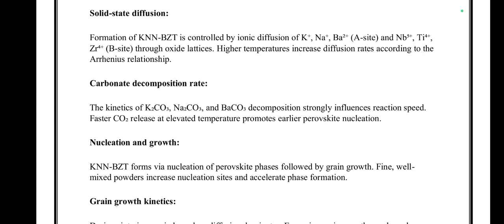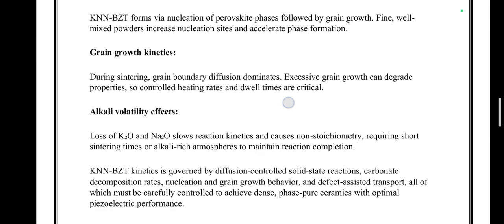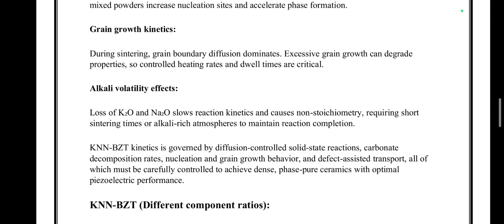Now, shortly, solid state diffusion, carbonate decomposition rate, nucleation and growth, grain growth kinetics, and alkali volatility effects explain the kinetics. Basically, KNNBCT kinetics is governed by diffusion-controlled solid state reactions, carbonate decomposition rates, nucleation and grain growth behavior, and defect-assisted transport, all of which must be carefully controlled to achieve dense, phase-pure ceramics with optimal piezoelectric performance.